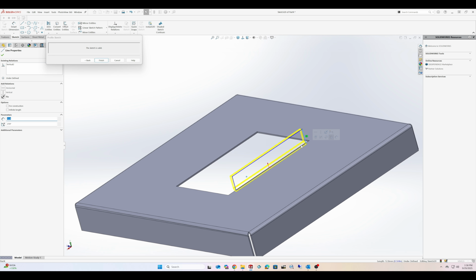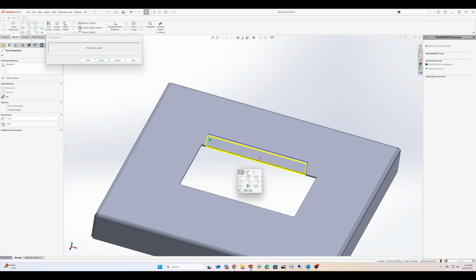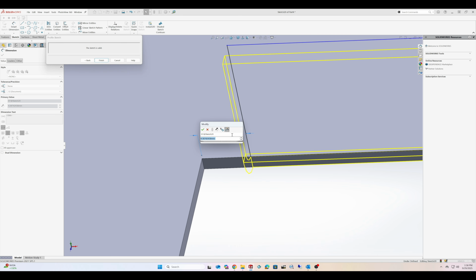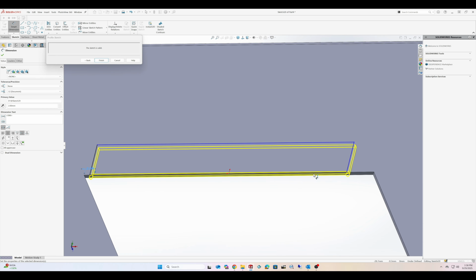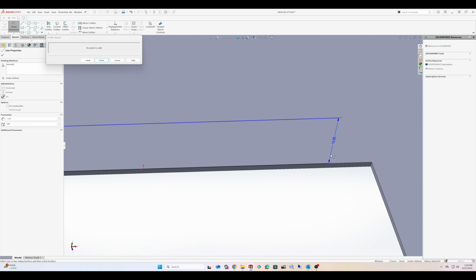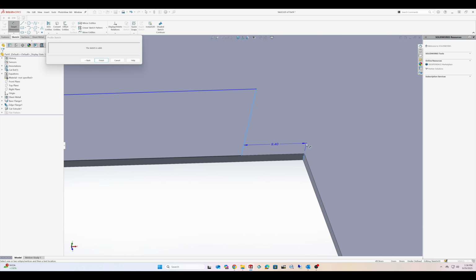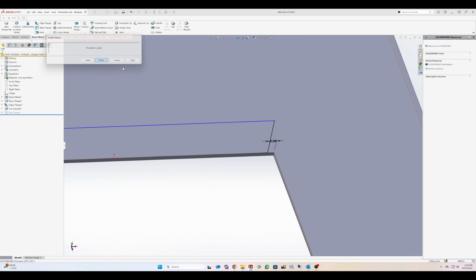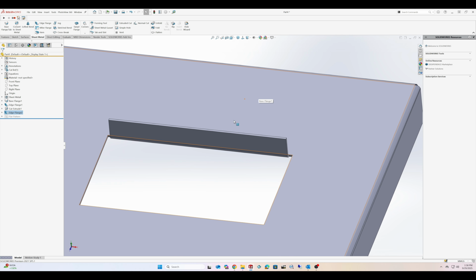After removing that center material, I use the edge flange tool again, this time bending that new edge outward with another 25mm flange. Now this step does two things. It creates the bend we need, and it helps define how the finished part will behave when folded. If you're working with real sheet metal, you know how important that accuracy is. Every millimeter matters when you're folding real material.